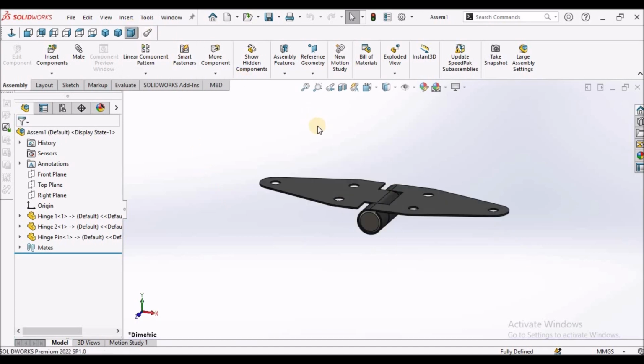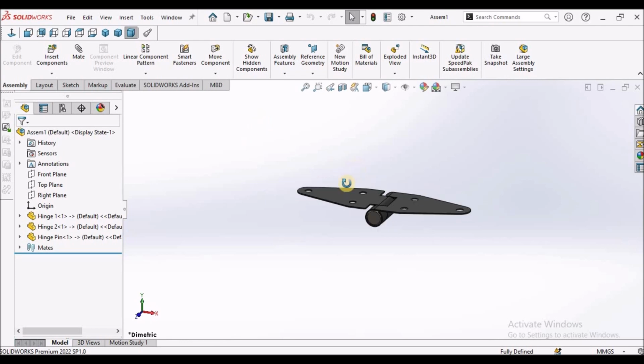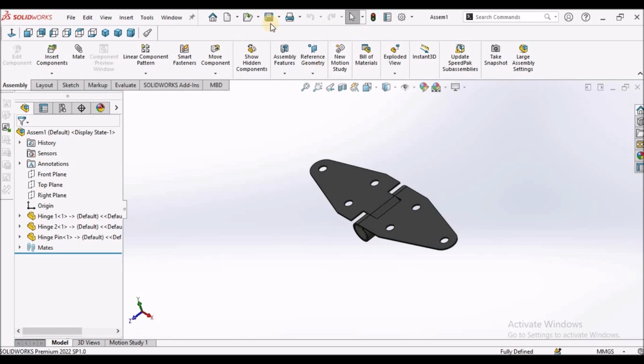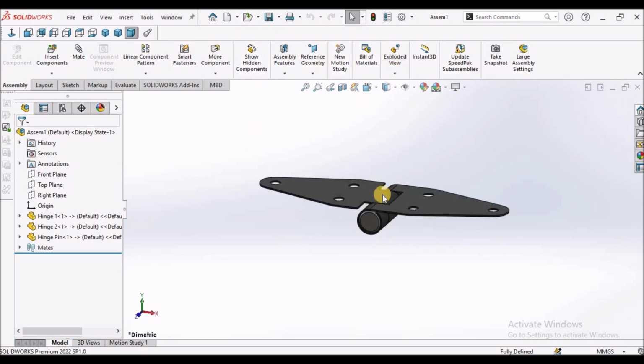So here in top down approach, two things we have to remember is we have to always use rebuild, so that if any errors occur in a sketch or features we can see, so that it doesn't reflect on all other components. And second thing, as soon as we create the components, we have to save the file, especially assembly file. Otherwise there is a loss of data if any failure in features or power loss. So we have to be careful during this top down approach.